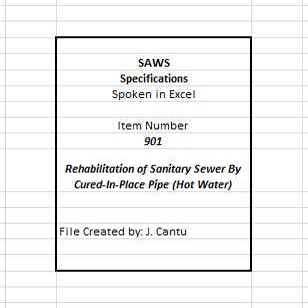Said price shall be full compensation for furnishing all materials, all submittals, sealing materials at manhole/structures and annulus, if required, launching pits, receiving pits, post-testing, shoring, bedding, backfilling, curing, site restoration, and all necessary, corresponding, and related work to complete the project. Site restoration, including but not limited to replacement of pavement, sidewalks, driveways, curbing, landscaping, sodding, etc., will not be paid for separately and shall be considered subsidiary to the CIPP rehabilitation bid items.